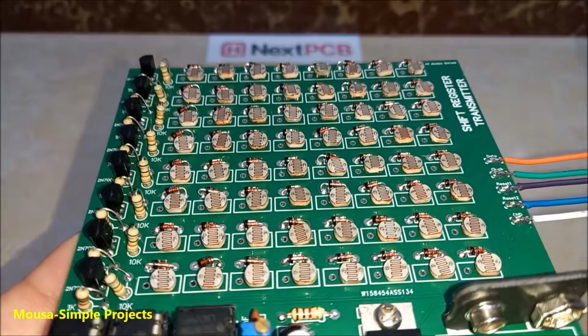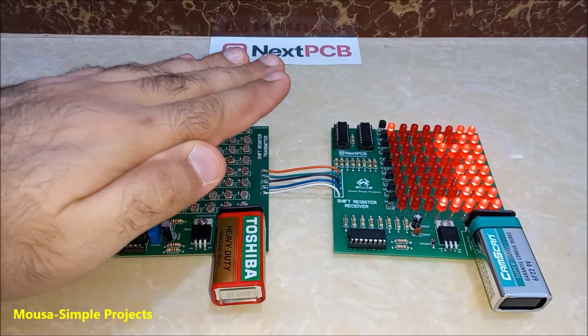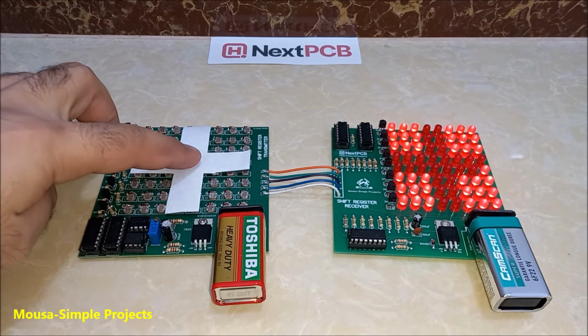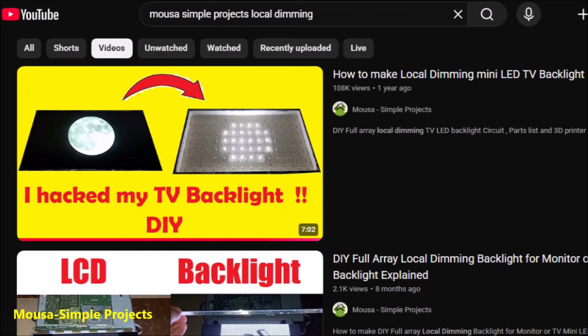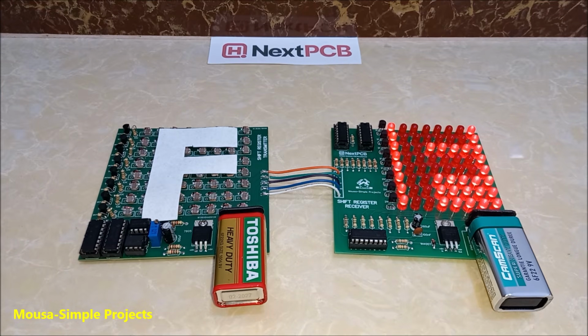Instead of using switches, you can use LDR light sensors. Now as you can see, it transfers the shadow of the objects to the LED matrix. That's so cool. You can change the light sensitivity by using this potentiometer. One of the applications of this project could be the local dimming that I made in a previous video, but you have to use white LEDs instead of red.